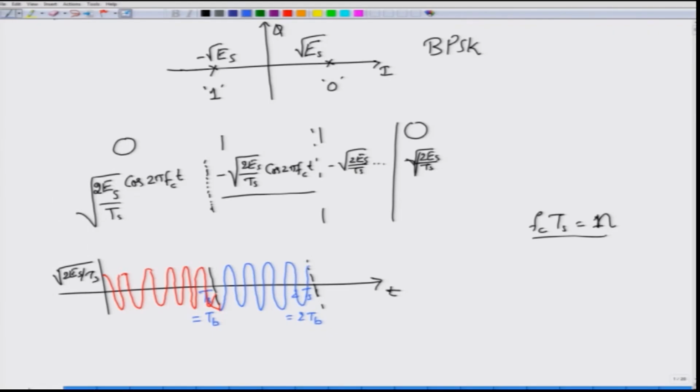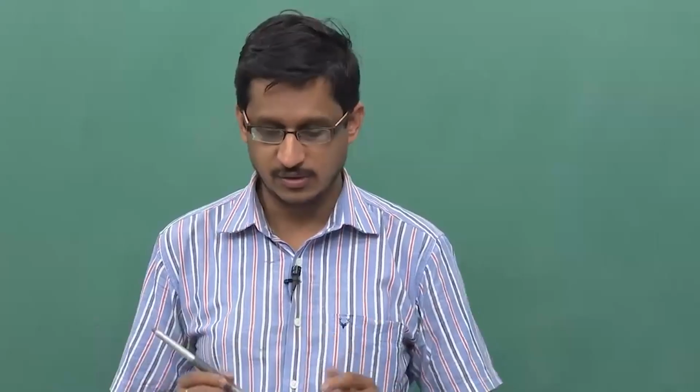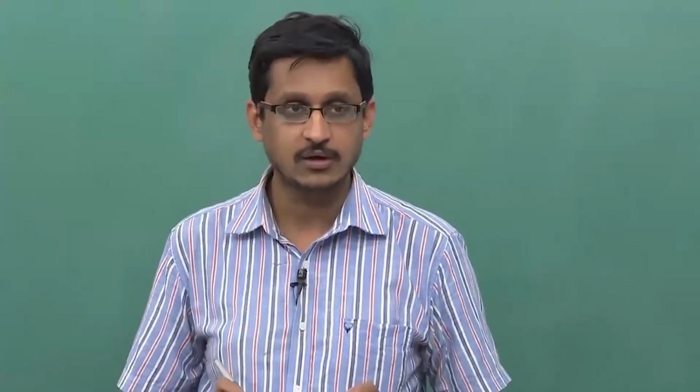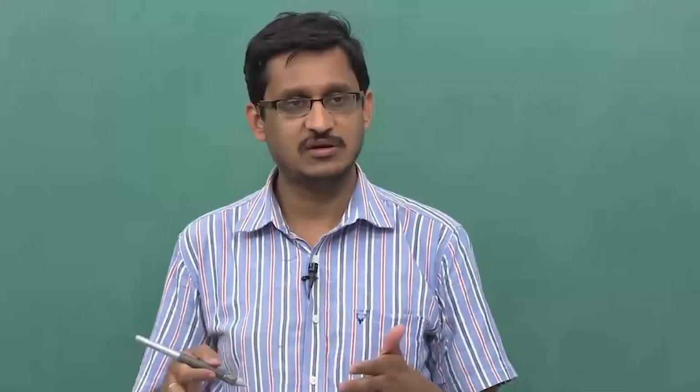Next I have to transmit again a 180 degrees. So, I have to switch over and then transmit a 180 degrees, and then I have to transmit a 0 degrees. So, it would actually be something like this. If you notice at these points there is a change in the phase. So, at this point the phase goes from 180 degrees to 0 degrees. This sudden phase transition between 0 and 180 degrees is important, because these transitions represent the signal transitions or the phase transitions corresponding to what sequence you are transmitting.